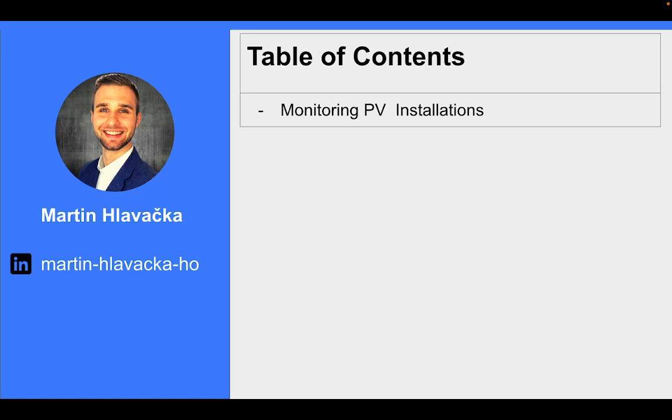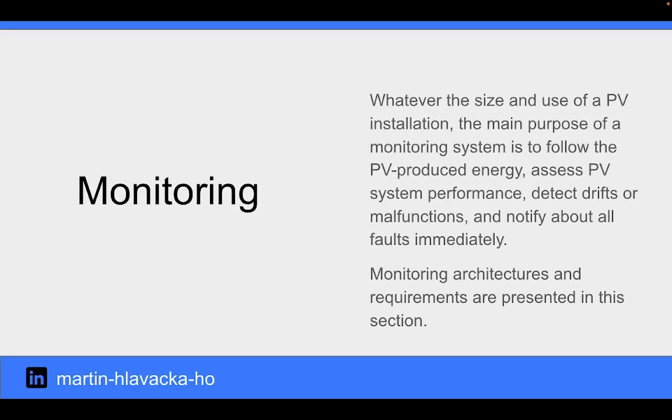In this video, I'm going to talk about PV monitoring. Whatever the size and use of a PV installation, the main purpose of a monitoring system is to follow the PV produced energy, assess PV system performance, detect drifts or malfunctions, and notify about all faults immediately.